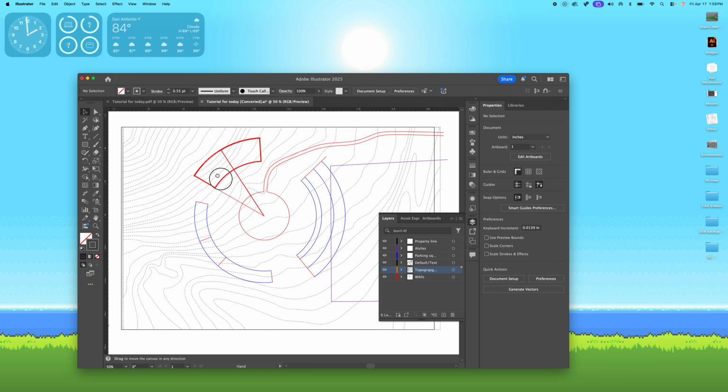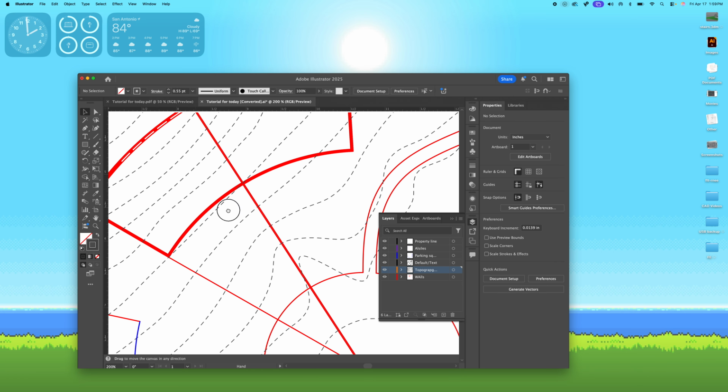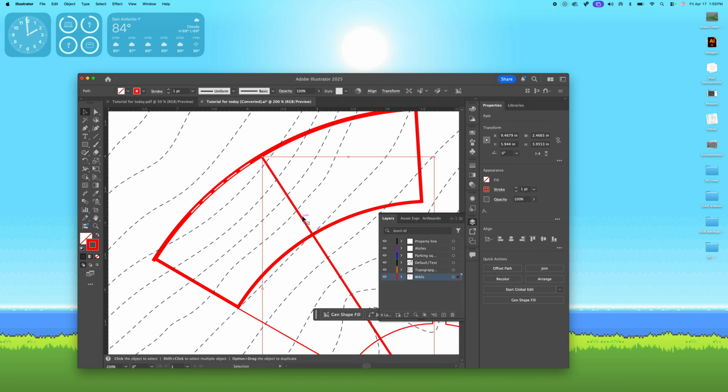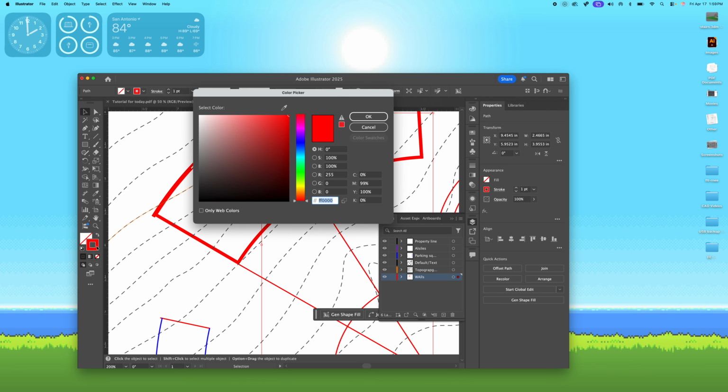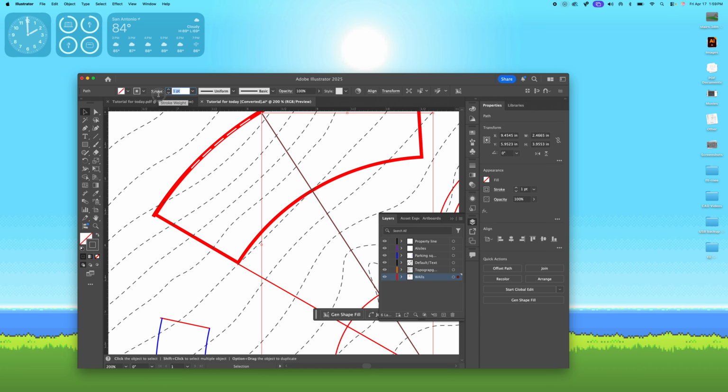Next thing is maybe my buildings or those walls that I did in Poche. And I do still have the ability to delete lines in here, right? So, even if I found, oh man, I forgot to delete those lines, or maybe I do turn them into somewhat of a construction line, let's do that. Actually, that's a good point to go over, because not every single line will come out of the printer. In fact, they say the smallest line that could be produced by a 600 DPI printer is 0.125 point.